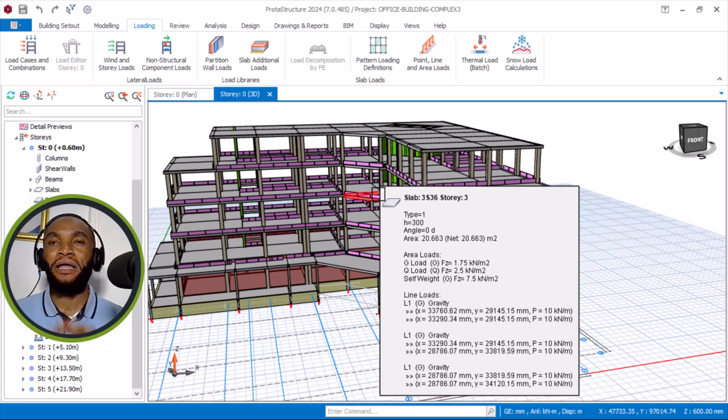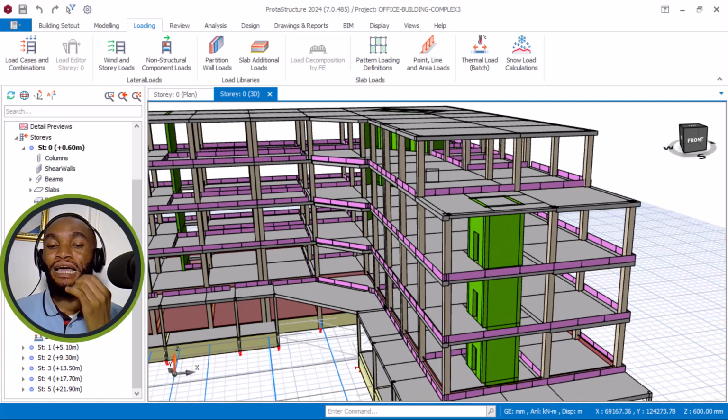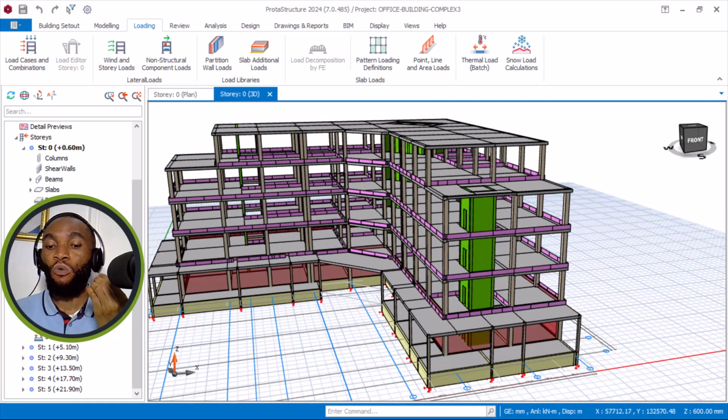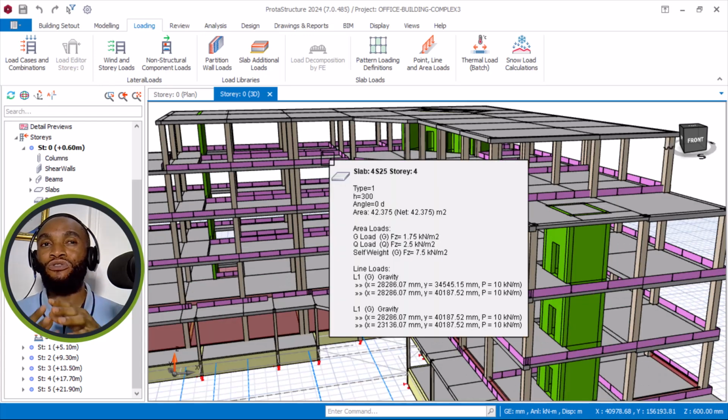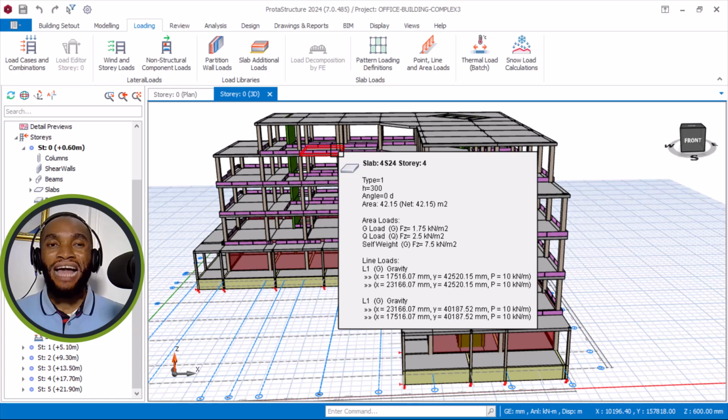You are going to consider bidiagonal reinforcement. You are going to consider that the link spacing is very, very vital. The link spacing between the beam and the column, the joints, all the joints, anywhere you have joints, in fact you must critically follow the principle of detailing seismic structure. Joints are very important, because once your joint does not follow the principle of seismic detailing, what happens is that as there is vibration, it will attack the joints first. It is the joint that it attacks first.